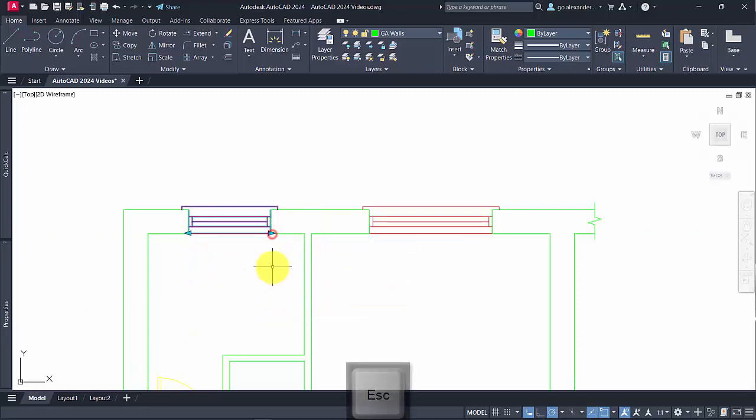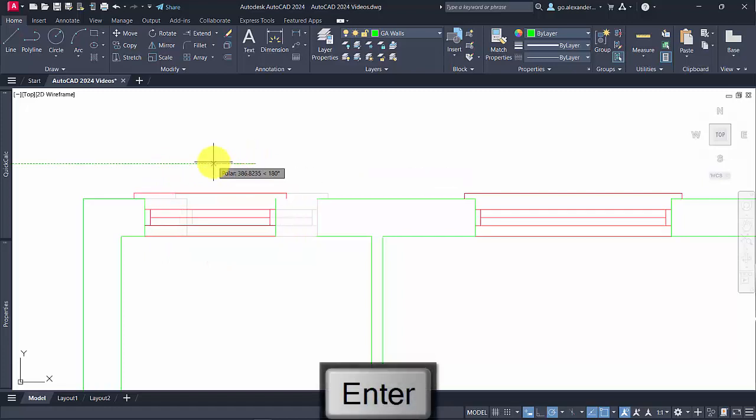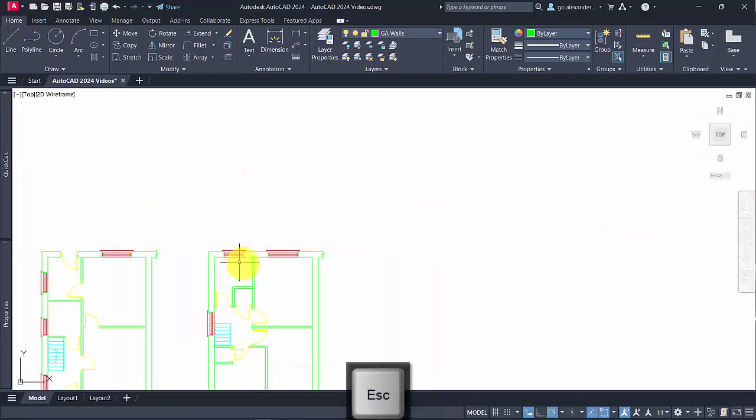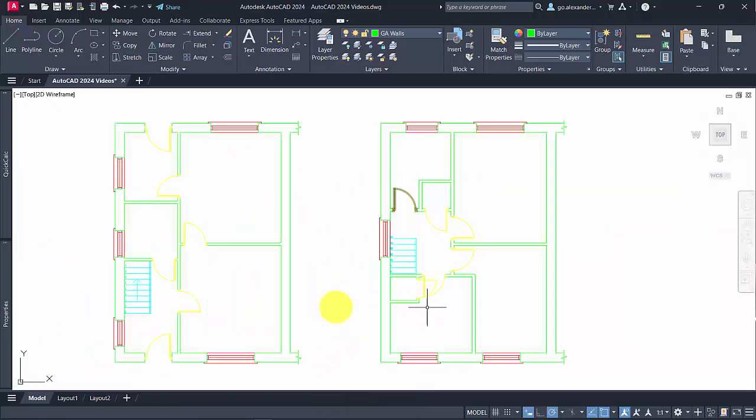It really is very handy that if you want to resize or do anything with those windows at any stage, everything can be moved using the stretch tool. Very, very easy. You might just need to resize the windows slightly afterwards. So that is the way the 2 floors should look now, with all of the doors and windows added in.